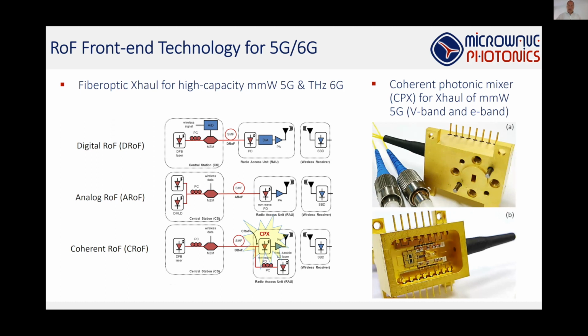So basically what you have here is one fiber with baseband optical data. There is another fiber that is used for a laser to upconvert to RF. This laser can also be integrated in the package if that is wanted. But here we have it externally, so it can be a tunable laser so that we can upconvert to any frequency which is supported by this front end. And then this device converts to E-band or V-band frequencies, depending on the integration technology that we are using.